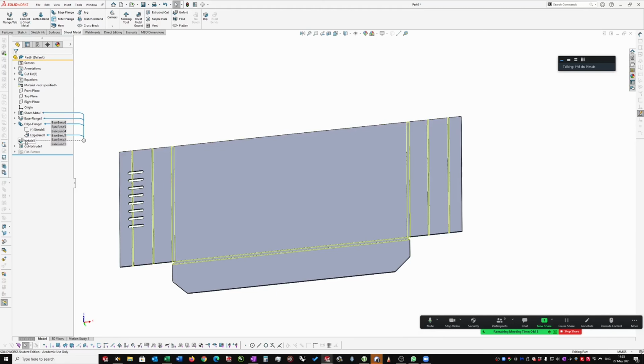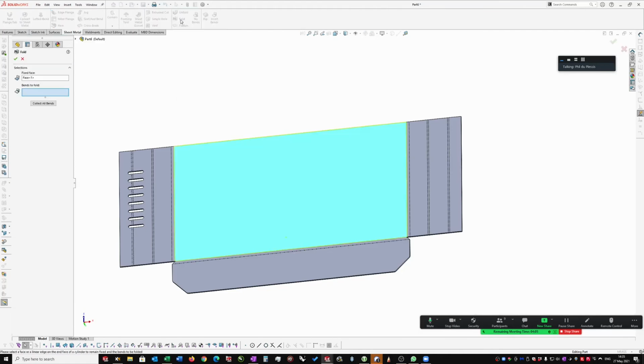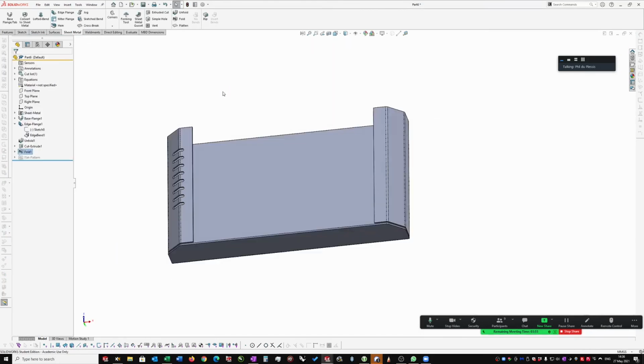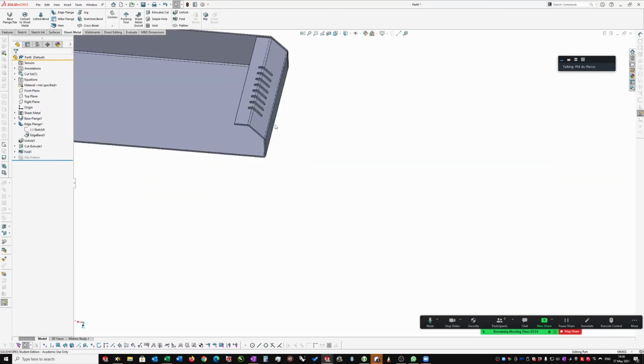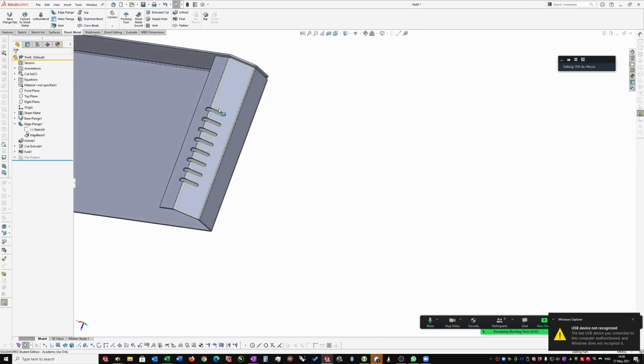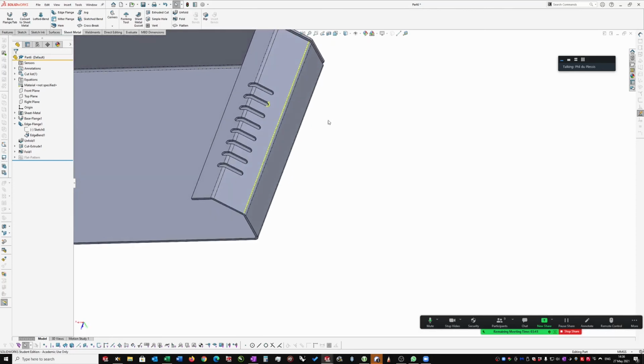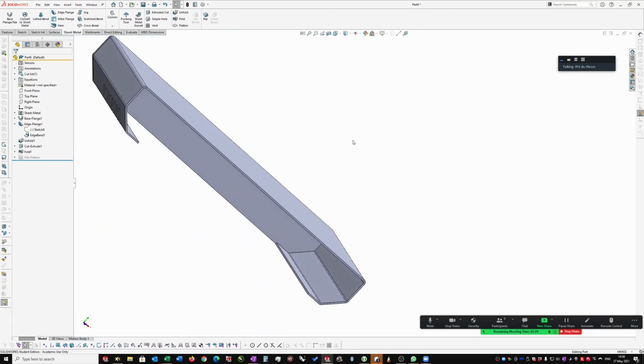This tells you a story. Unfold, and then I did the cut extrude, and now I'm going to fold again. So under unfold is fold. It's already selected the face which I selected to unfold. I can simply say collect all bends. It'll collect them. When I click OK, it'll push everything together, and I have the slots going across that bend. So that's how you cut slots across a bend. I could have made those extend, of course, and that's the basics of it.